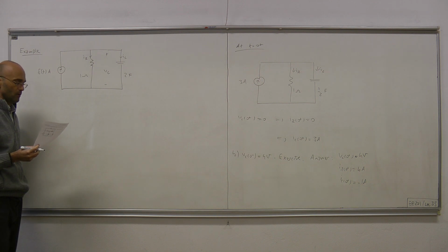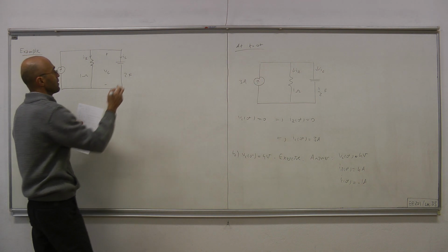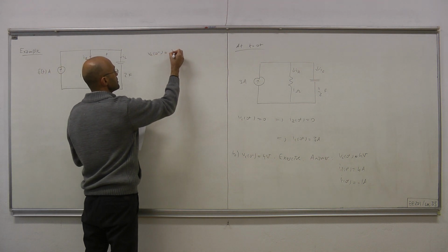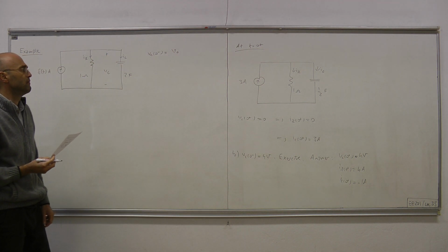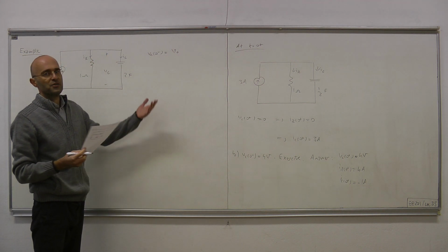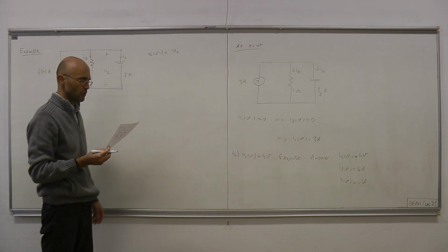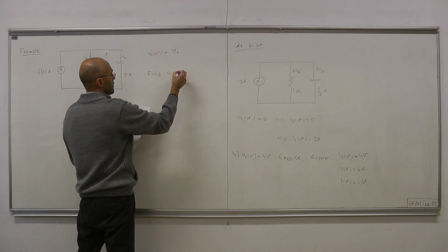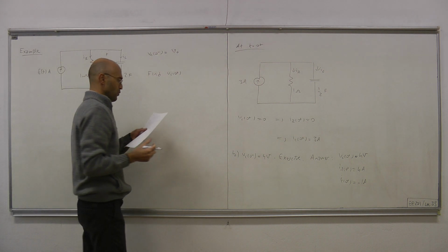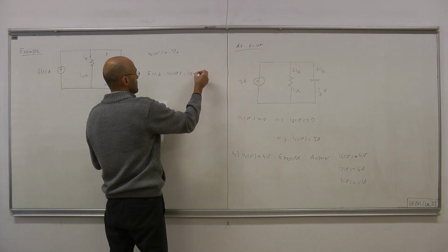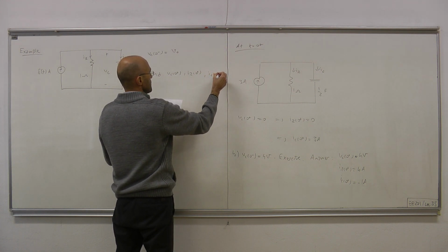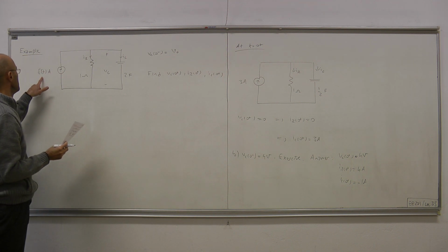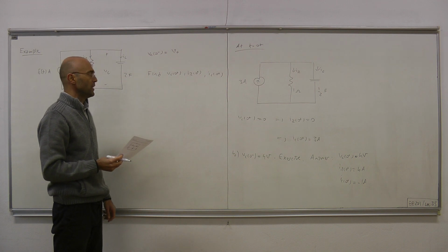This is our circuit. 3 parallel components. Initial capacitor voltage is something which we denote by V0. Okay, minus 6 volts, plus 17 volts, whatever you like. And then find, in terms of V0, VC0 plus, IR 0 plus, and IC 0 plus. Okay, we're going to figure out those quantities just after this impulse does what it does.